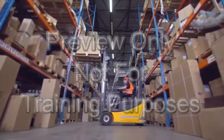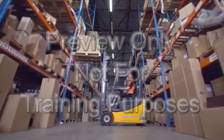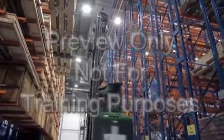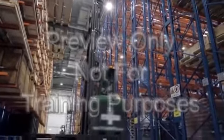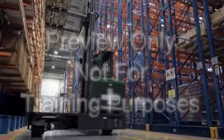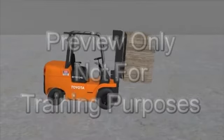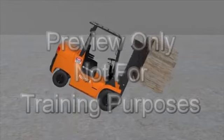Carefully extend the reach mechanism of the truck forward when depositing the load. Use extreme caution when tilting a load forward or backward, especially when high tiering and on the top tier. Improper tiering of a load can cause a truck to tip over.